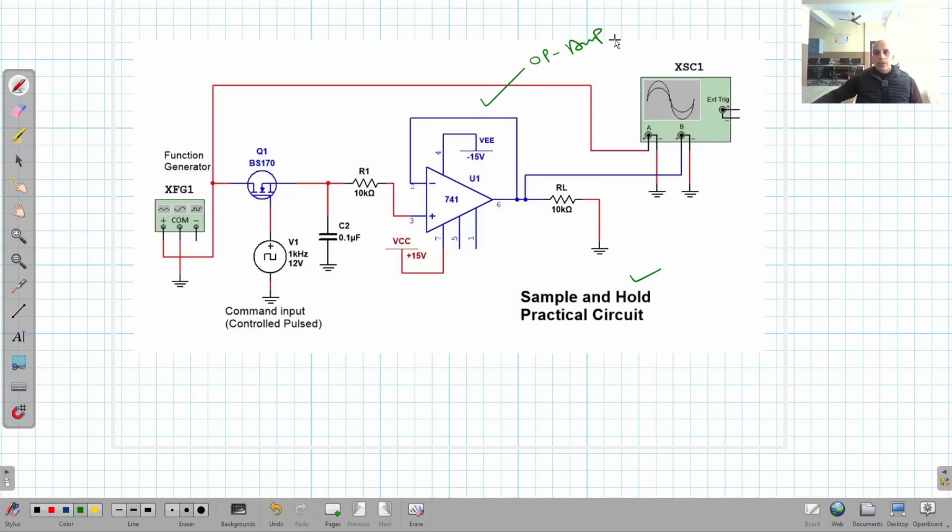As I told you, this circuit is going to make use of an amplifier, and obviously it is an operational amplifier. The operational amplifier used here is a voltage follower. We know from the theory of op amps that this circuit is a voltage follower. The inverting input is connected with the output, whereas the non-inverting input is connected to the resistor and then to the capacitor. It means the incoming signal is applied across the non-inverting input of the op amp.